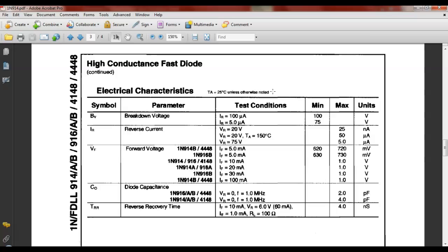So we consider that on most data sheets, that's what we mean by room temperature. So on a diode, if heat goes up, leakage current goes up. If it's ambient temperature, and ambient temperature is the temperature where it's mounted, right? You understand that? It's working in. So it might be 75 degrees outside, but you got this sucker in a cabinet, and it's 100 degrees in the cabinet. Well, that would be the temperature that we're looking at.